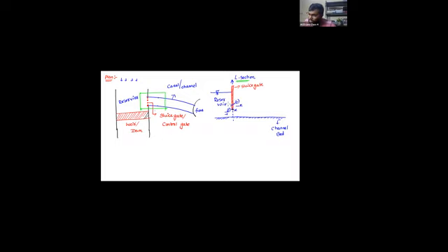And tomorrow I lift the gate to here. Then the water level will rise or not? Yes or no? When the water level rises, more water will travel towards the downstream side. Then the velocity is not the same. Yesterday velocity is different, today velocity is different. Yesterday discharge is different, today discharge is going to be different. Yes or no? Why? Because I operate the gates suddenly,